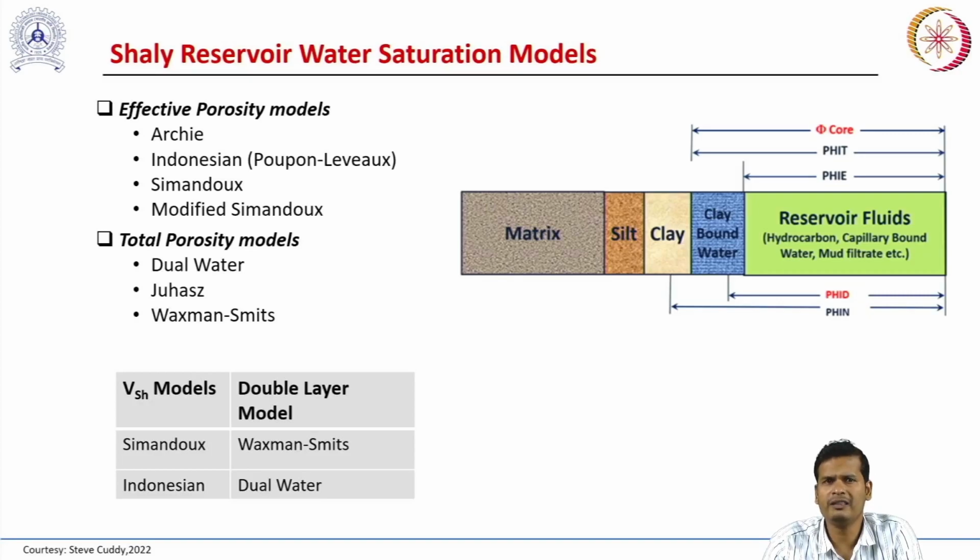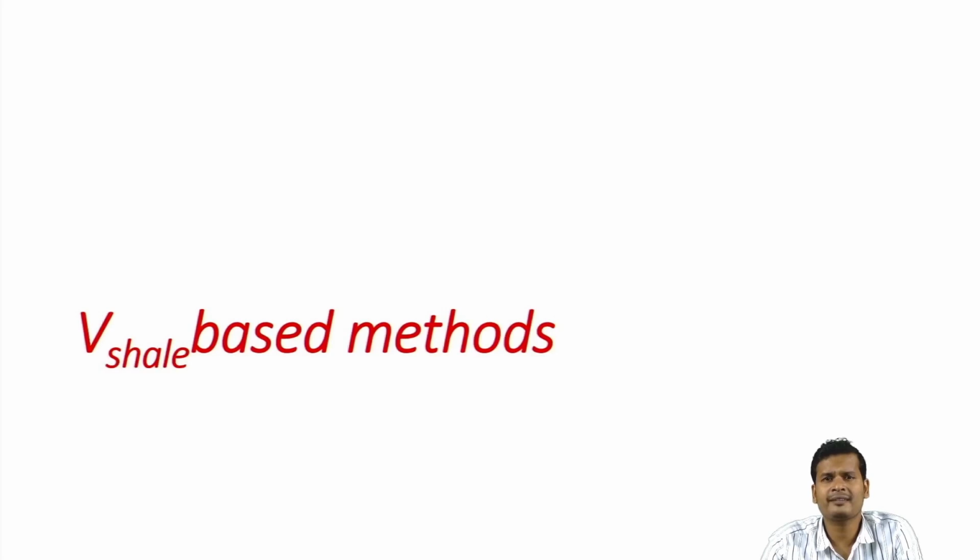So all these models try to model the clay behavior and prepare a water saturation model for saline sand by including the clay conductivity along with the formation pore fluid conductivity. So let us discuss some of the different saline sand equations. First we'll consider a few of the shale volume based or shale content based methods.